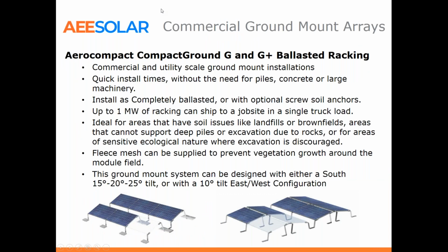Ground mount arrays, doing a lot of Aerocompact ballasted ground mount arrays too, especially Arizona, New Mexico, Texas, Midwest, places that have light to no snow conditions. I've done a lot of Series 200 ground mount arrays, and those are typically multi-day installs, needing to first lay it out, dig all the piers, the poles, cut all the pipes, set the pipes and the poles in place, wait for the cement truck, wait for the cement to dry, then assemble the array.